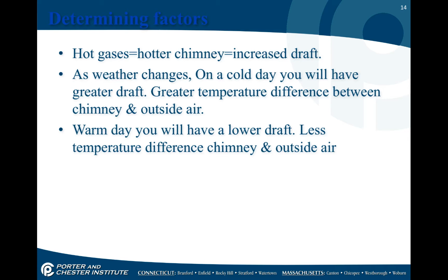Now, you have to deal with this factor because on weather changes, on cold days you'll have a greater draft. So midwinter your draft may be excellent, because there's a greater difference between the chimney and outside air. But for those people who use an oil furnace or oil burner in the summer months to heat hot water, you could have a very low draft on a 90-degree day where the boiler's running to heat hot water.